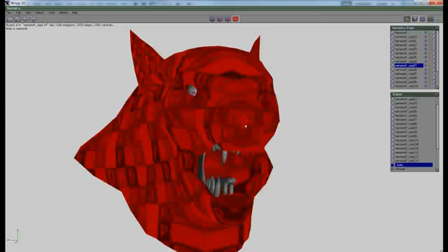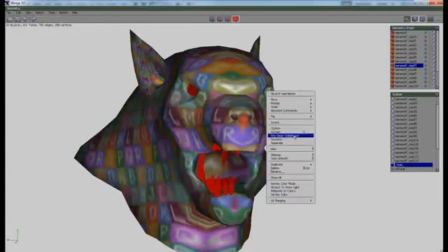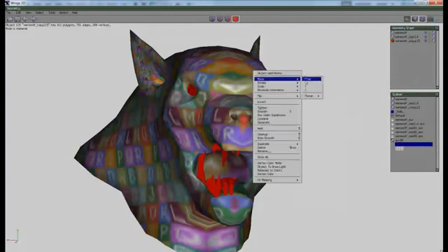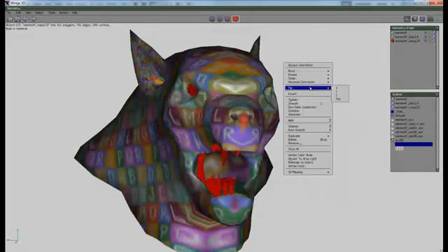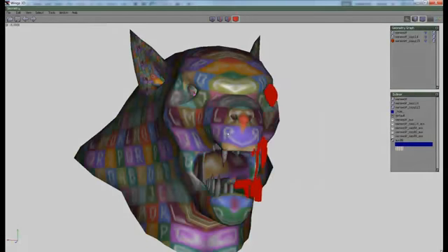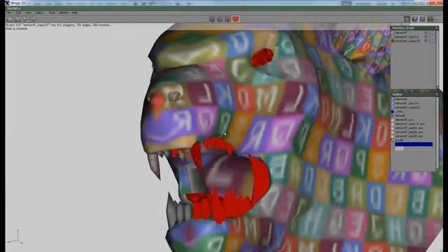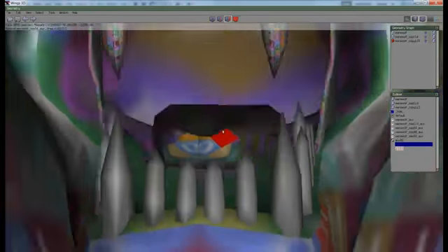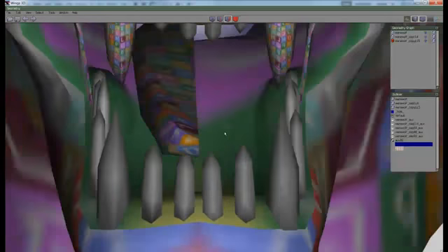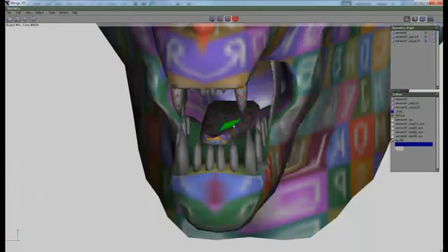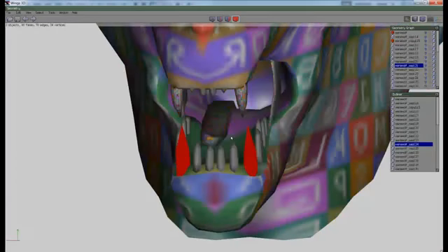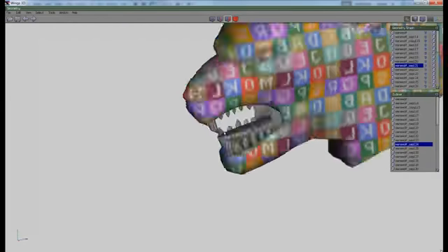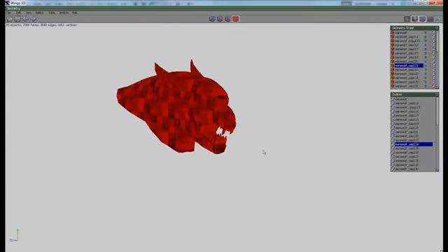Let's Control I, and then combine, duplicate, click to duplicate them so it's on the same position. And then flip on X, move it just a little bit. Gonna delete this one and then just mirror it. Whoops, I still need to separate it first and mirror it, and that should be right about it. So it's roughly UV mapped. It still needs to be positioned.